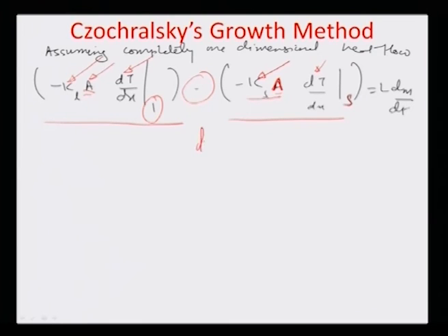If we assume that the rate at which the solid material gets formed is dm/dt, as you can see in this illustration, and L being the latent heat of formation, which is how much heat per kg is lost in order to form the solid, then L dm/dt is really nothing but the rate of heat loss in terms of formation of the solid bonds.